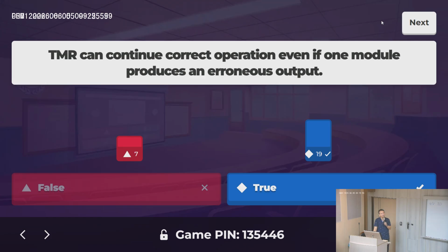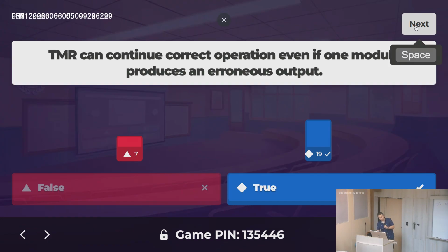We will have a smaller MTTF. So please also try to clarify what is the reason. For TMR, its purpose is not to extend the MTTF or the lifetime of our products. Its MTTF actually will be shorter. So what is the reason and what is the advantage that we still try to use TMR? That is very important for TMR here.